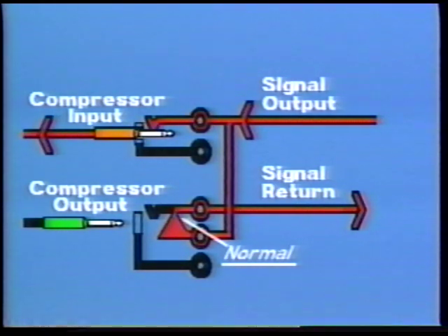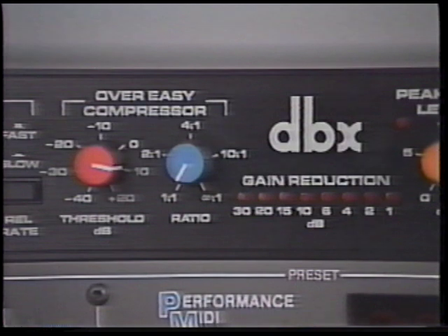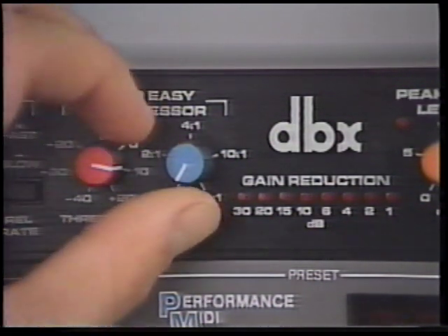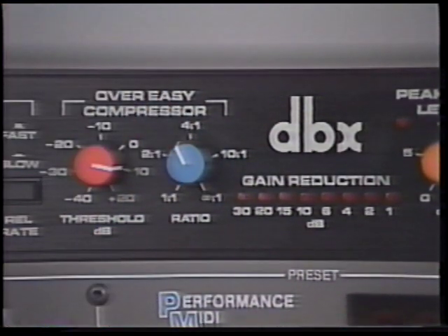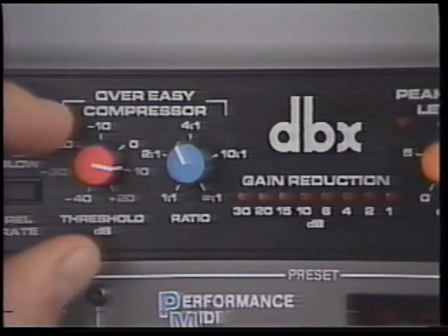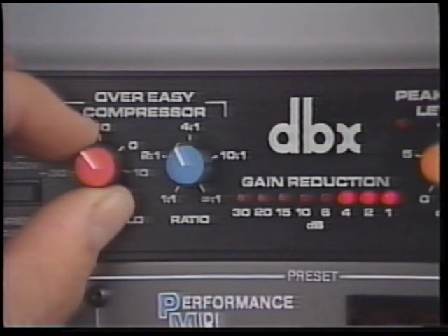Only when you plug in the compressor limiter output to the return will the normal be broken and the insertion completed. So, before connecting the output of the compressor into the signal path or access return, roughly adjust the compression so that the level of the signal won't suddenly jump 200 dB and blow everybody's heads off. Most compressor limiters will have gain reduction indicators or meters. Roughly set the ratio control for the severity of compression you think you'll need. Adjust the threshold until you see a certain amount of gain reduction occurring on peaks, as indicated by the meter.